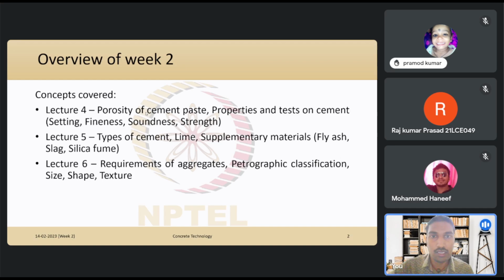One, there is porosity in the cement gel, as hydration takes place in the cement paste, and there is also capillary porosity. Water takes up some volume in the concrete, and with time, as hydration occurs, the space that was originally occupied by water will be filled by the hydrated products, and some of the volume that was occupied by the water earlier will still remain empty. That is the capillary porosity. That is with respect to the porosity of cement.